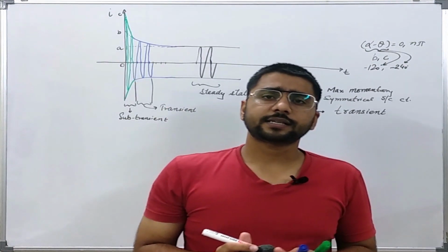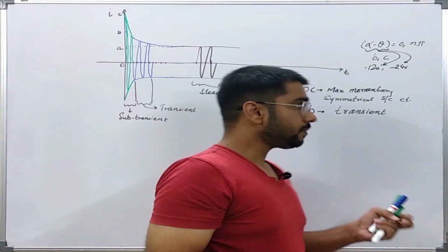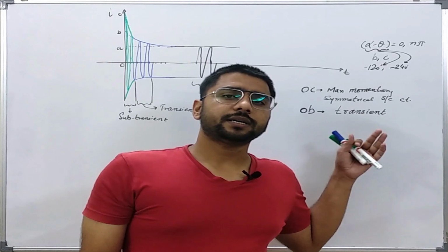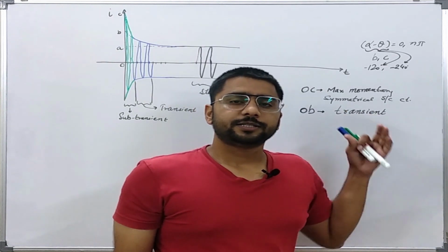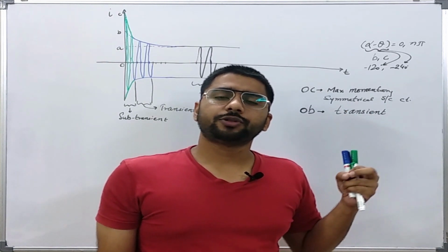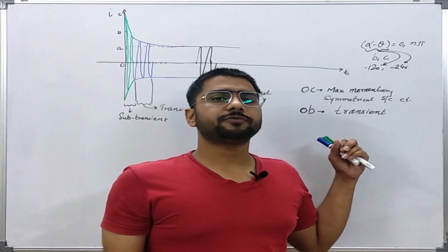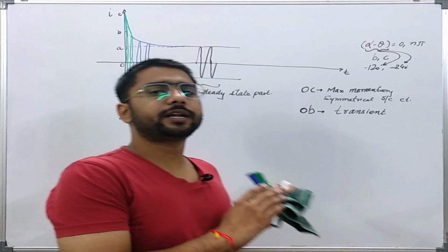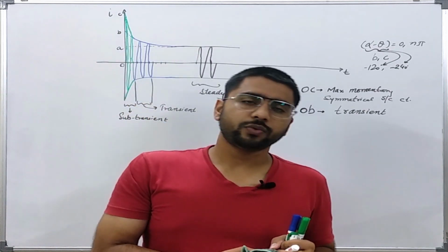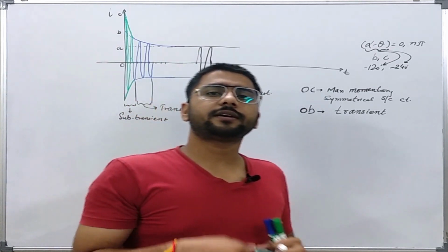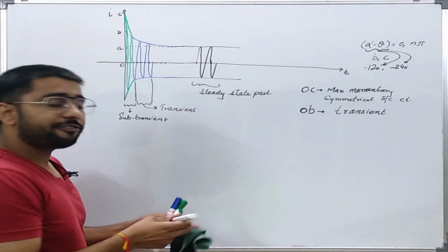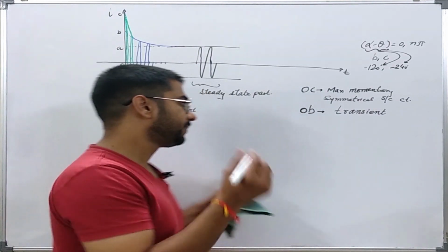Now in a synchronous machine, due to the flow of current in the armature, there will be a change in the air gap flux due to the armature reaction. Because of that, the voltage induced will be different. So to cater to those differences, we define various reactances offered by the machine. Okay, and we define three reactances.